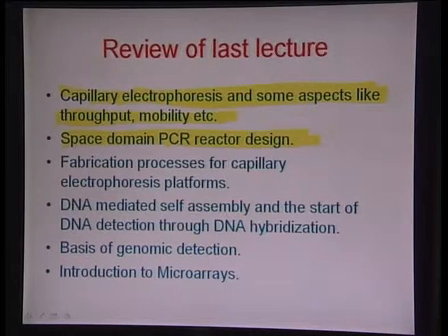So spatial domain PCR reactors have been designed, and in these cases you have to design for the maximum velocity for robustness of design. Even though the fluid is moving at its peak, the PCR fluid has enough interaction time with the temperature zones to get denatured, annealed and extended according to whatever process step it is in. Space domain PCR comprises a channel which is engraved over these 3 differential heat zones and then given multiple turns. So we designed such a reactor device.